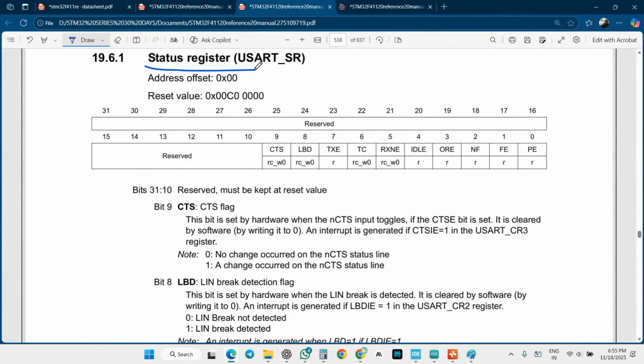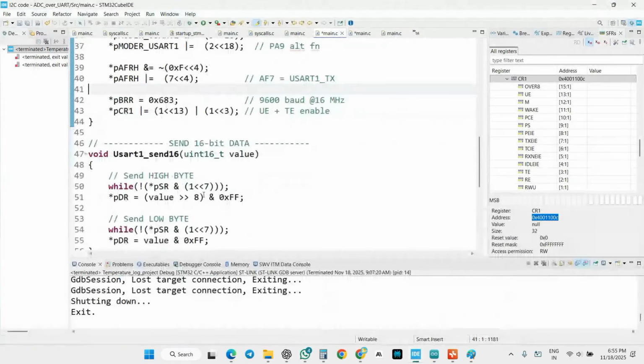Status means what is the status of any process which is currently happening, whether the process is in progress or in halt. That needs to be found out. The microcontroller functionality is mostly detected by the SR register. Here the TXE bit is there. So whether the data has been sent and the buffer is free or not is checked, and by checking that condition we transmit the data.